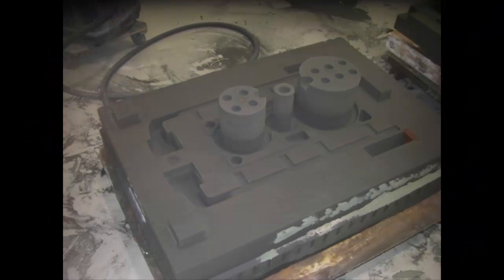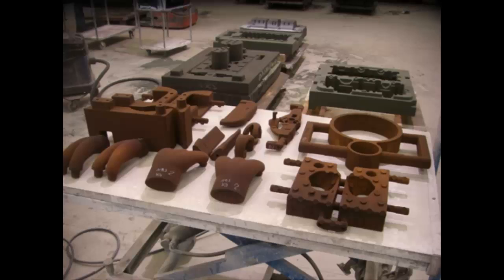In the following image, we can see a horizontal cross-section view of the mold used to cast an engine block, and also some of the cores that are used for this engine block. These cores allow the engine block to have hollow parts, which serve as passages to allow the air to flow through the engine as needed, and some will be for coolant to flow through, making sure the engine does not get too hot. The second part we'll be analyzing today is a piston.